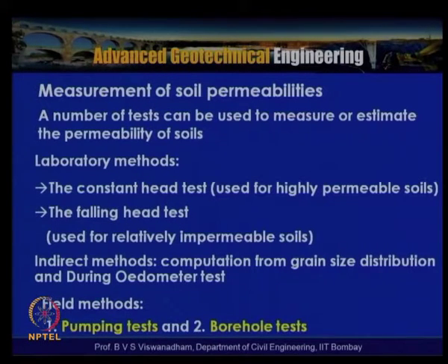In the field, the possible methods are called pumping tests and borehole tests, which are popularly known as Packer tests, conducted with single packer or double packer systems.